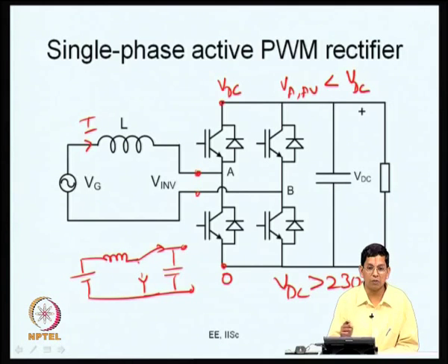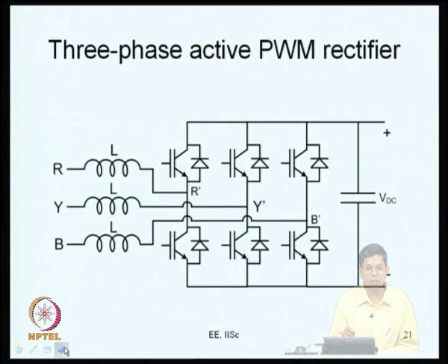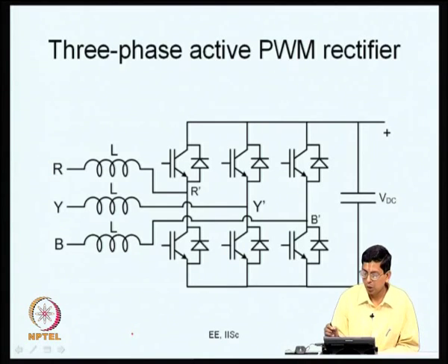It is a boost converter. What you want to emphasize is that this is a boost converter. You can call it a single phase AC to DC boost converter with power factor correction. The same thing can also be done in the 3 phase case. So, you have a 3 phase converter and you have 3 inductors like this, and you can connect the load on the DC side if you want rectification.